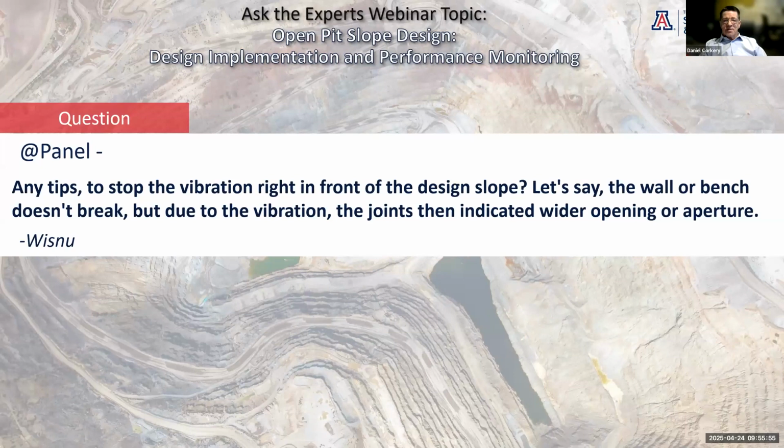So clean the face, and if you want to minimize them, there'll be things like reducing the hole diameter as you're getting closer to the final wall, and for trim blasts you might want to have a lower hole diameter, or any other methods to minimize the amount of explosive damage or energy that's coming from those holes.